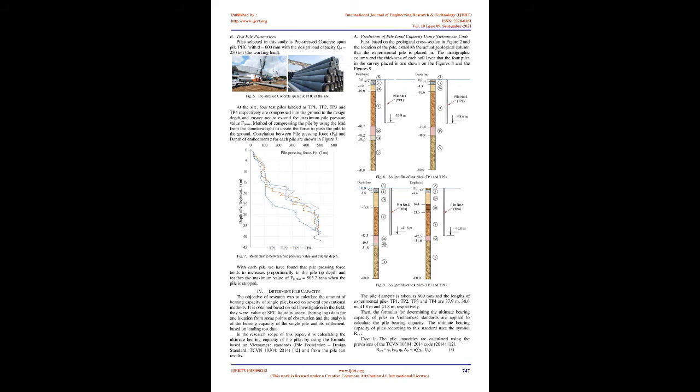Nabil [3] studied the group effect of bored piles based on the field test performed at a site in South Surra, Kuwait. The study also includes load testing on single piles in compression and tension states. Two groups of piles were made, each group consisting of 5 piles. The spacing of piles in the selected pile group is 2 and 3 times the pile diameter. The group coefficient value found is 1.22 and 1.93 when the distance between the 2 piles is 2d and 3d respectively, where d is the bored pile diameter.